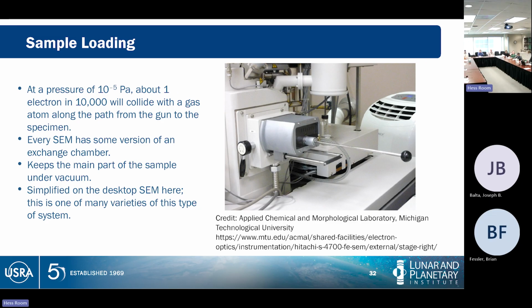Every SEM will thus have a boundary between where your sample goes in to get put into the vacuum, and where the sample comes out. Sample exchange is thus something everything is going to have to do. Do you keep the vacuum on all the time if you're not using the SEM? Yes. Unless it's down for service, or the power's out, keep it under vacuum unless there's some reason not to.